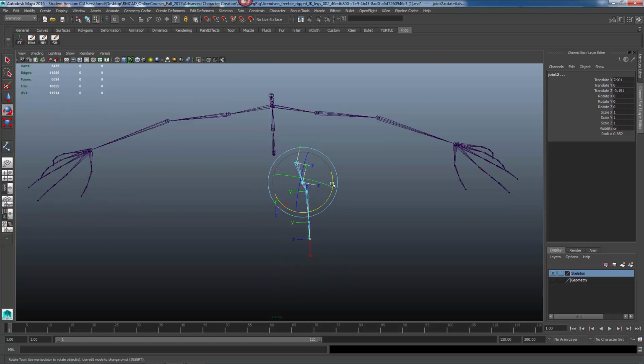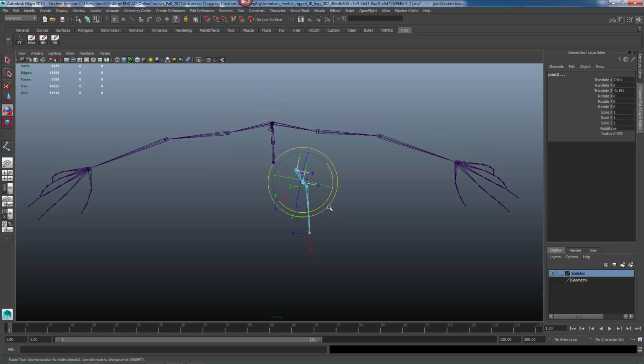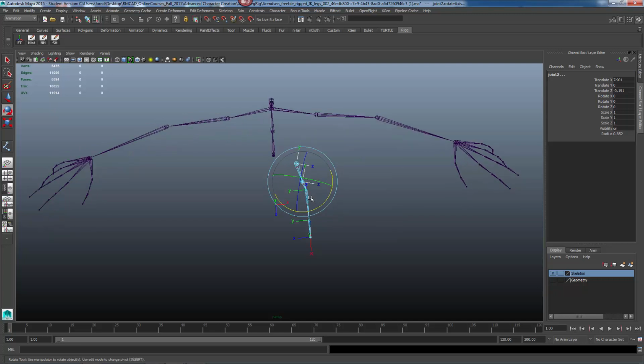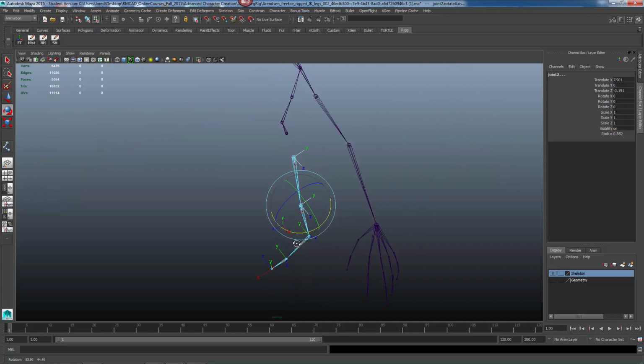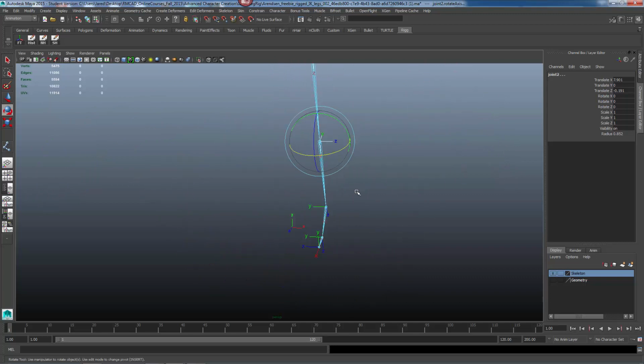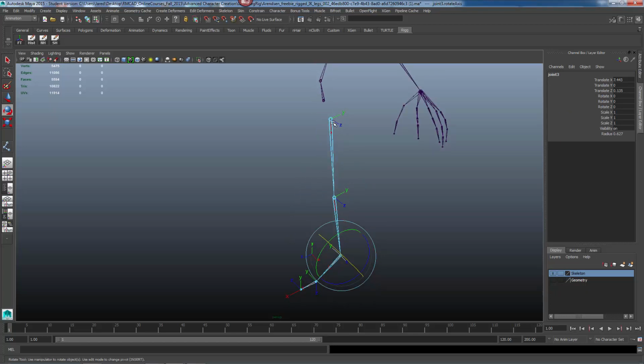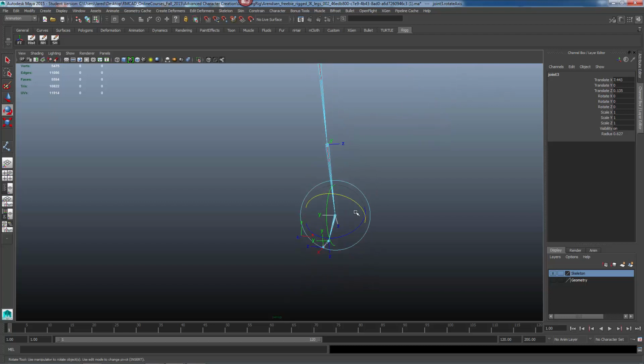And I want them to point outward, not at some funky angle, because this is going to be bent at the Z-axis. So that's going to get my walk cycles and all that good stuff in forward kinematics mode. Oh, and inverse kinematics as well, because they're going to be based off of our orientation to begin with. Okay, Y we don't worry about, because once we align X and then Z, Y falls into place. So that makes life easy for us. We'll hold down J, click this and drag it until it snaps.